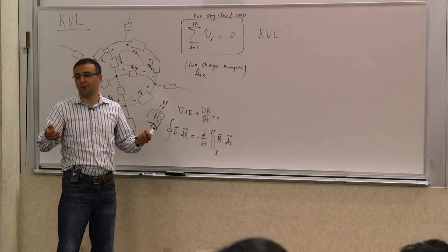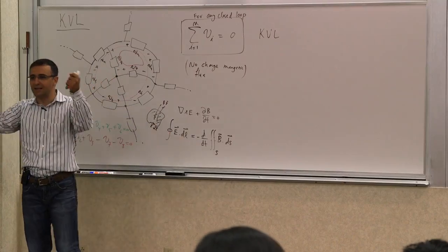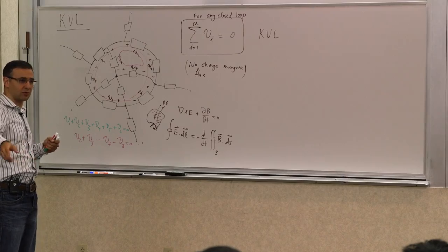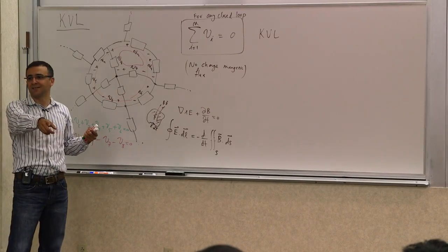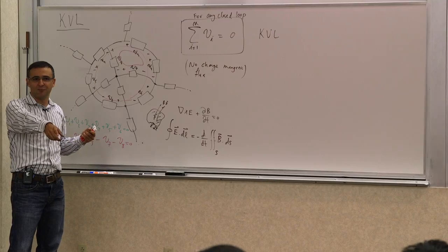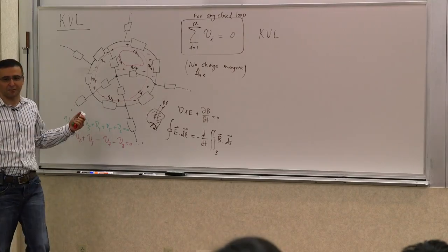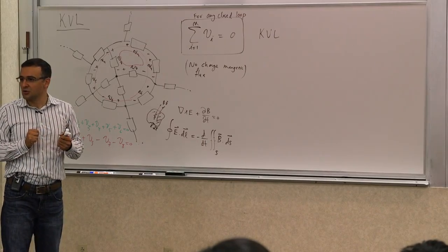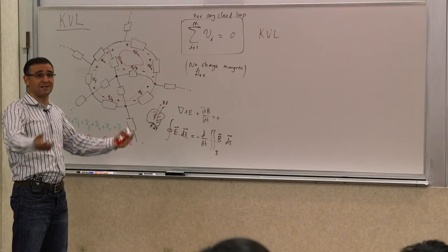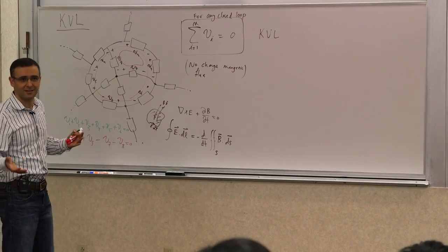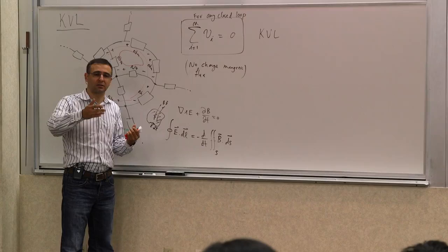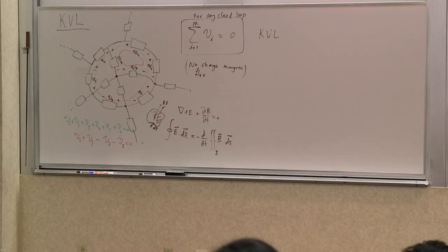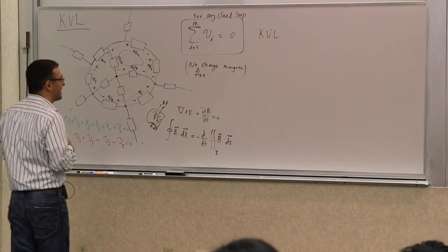All the power transmission network is based on transformers and magnetic coupling, because you do not distribute, I'm sure everyone here knows, the 110 or 120 volts. And there's a good reason for it, which we can discuss in a few minutes when we talk about the power of a resistor. So you distribute hundreds of thousands of volts, and then you bring it down to 480 and 240 and 120 and things of that sort that you use locally. Those are perfect examples of that. There are many, many examples.